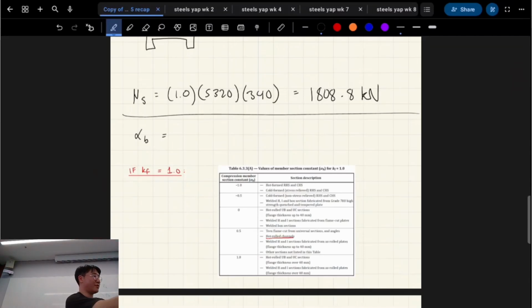Compression's different. You can imagine if I press down on this, it's going to start to buckle, essentially. Say I had the same kind of material, like wood, that's this short instead. It's not going to buckle. It's going to purely be based on a yielding, crushing kind of failure. And same thing if I had a stick that was the length of this whole room. I push down a little bit, you're going to see major buckling effects. So that length is going to have a quadratic effect on how much strength we have, because it's going to be governed by buckling now.